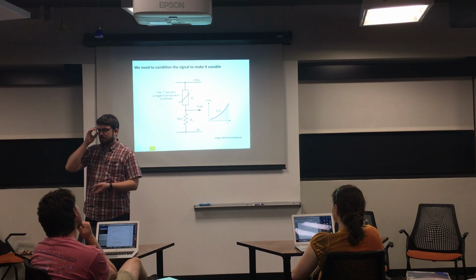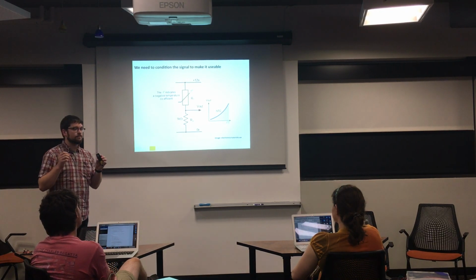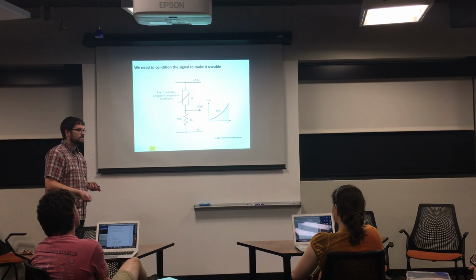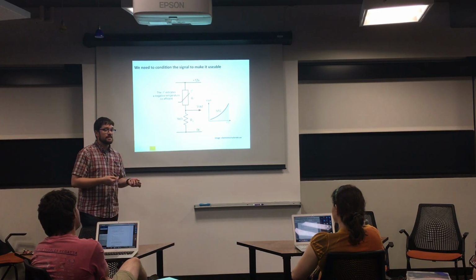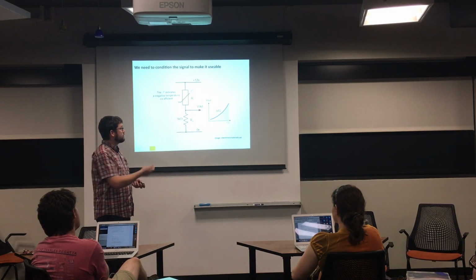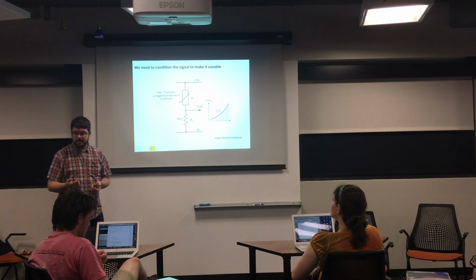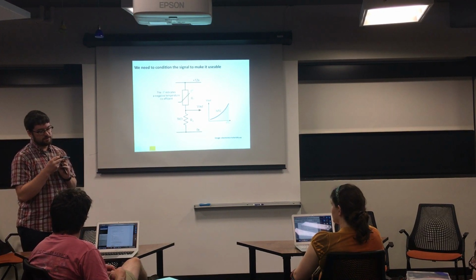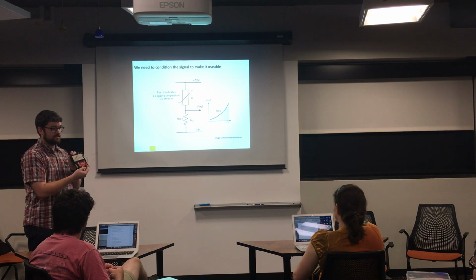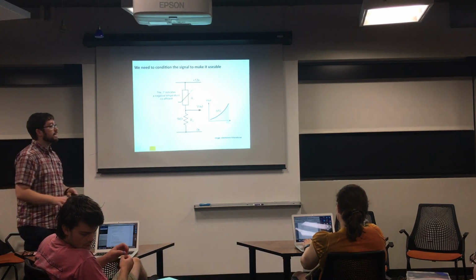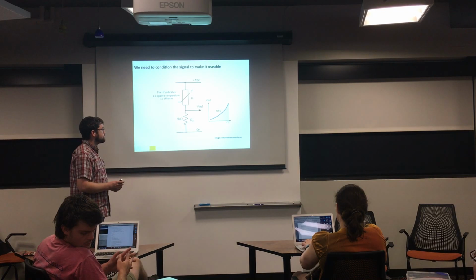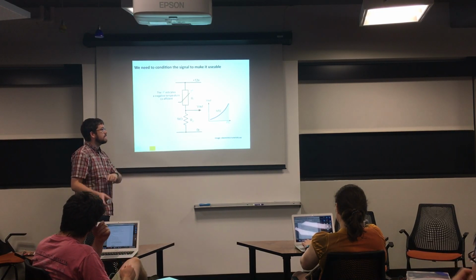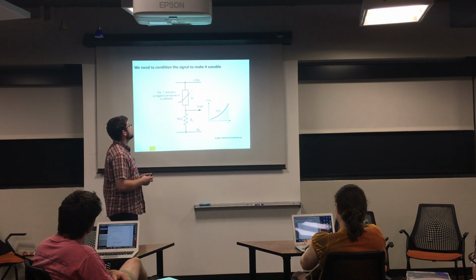But if you notice on your Arduino, there is no resistance port. There's nothing that you can connect to measure the resistance of something. So we have to condition the signal into something we can measure. On the Arduino, we can either talk digital signals, which this is not, or we can measure an analog signal using these A0 through A5 ports here on the side, where they take voltage and have an analog to digital converter on them. So we're going to use something, in this case, called a voltage divider, which we'll go over at the end, because it's what you actually build on your breadboard.